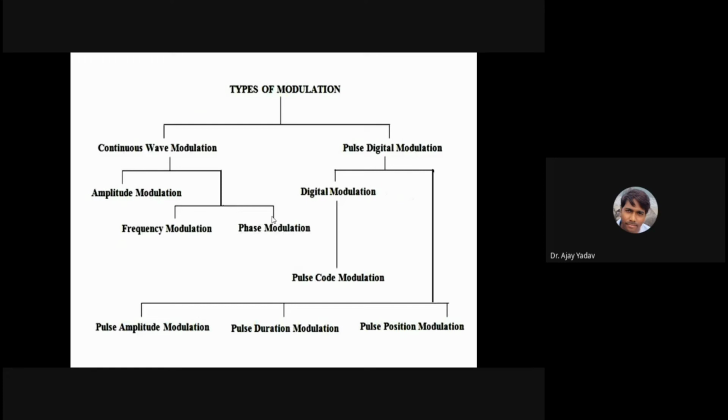So there are basically three broad categories in the electronic communication system. Simplex type, where information can only be received. Half duplex, where both transmission and receiving are possible but not simultaneously. The third is full duplex, where you can transmit and receive simultaneously. Is that clear to everyone? Yes, sir. Okay. Now coming to this point, modulation.